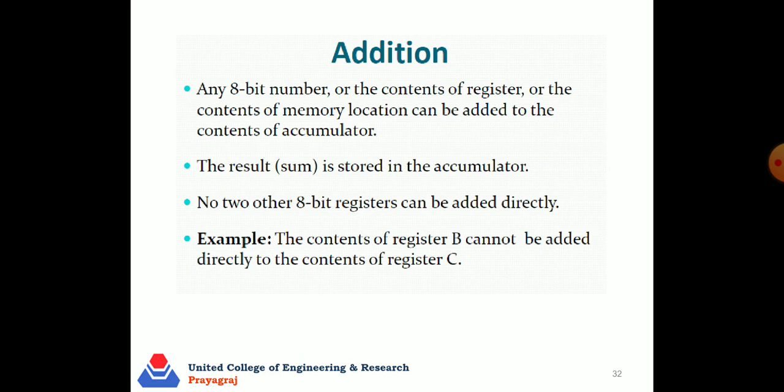In data transfer instructions, no flag is affected. But in arithmetical and logical operations, the flags are affected according to the operation or instruction. It's a very important point.